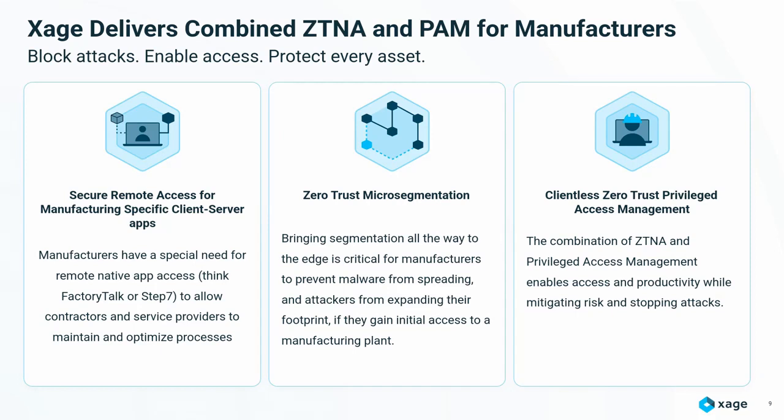And then there's the user to application control, which limits the ability of the user to access applications other than what they are explicitly allowed to do. One of the most common attack vectors against OT is exploitation of public-facing applications. So by denying access by default, unless explicitly allowed by the fabric, operators can reduce their attack surface against one of the most successful attack tactics.